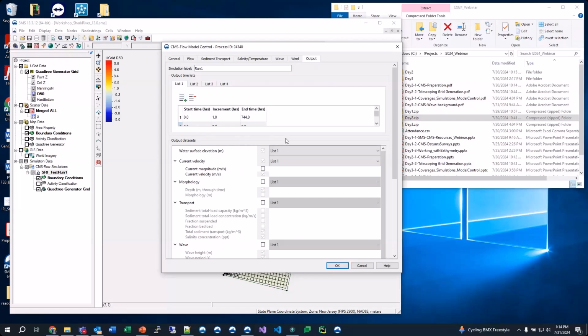You can have multiple lines here. So if you know, okay, I want hourly increment for the entire time, but during this one period that I have a storm, it might be between hour 28 and 40, you want half hourly output, you can do that, and it'll create this, and it will have times at half hourly during this window and then go back to hourly for the rest. Something that we don't typically do, but we can if it is needed for the user.